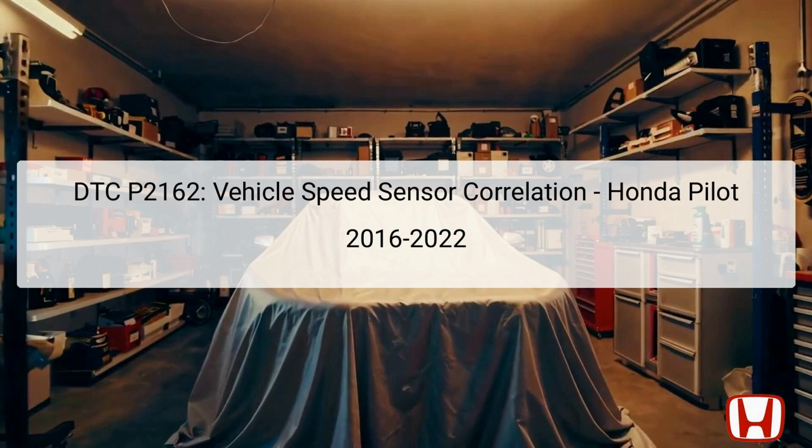The vehicle's speed sensor plays a crucial role in relaying real-time speed data to the Transmission Control Module, TCM. When the TCM detects an inconsistency or failure in the speed sensor readings, it triggers the P2162 code. As such, diagnosing this DTC entails a careful inspection of electrical connections and continuity within the vehicle's wiring system, specifically related to the sensor and TCM connections. Understanding the implications of this code is vital for maintaining optimal vehicle performance and safety.